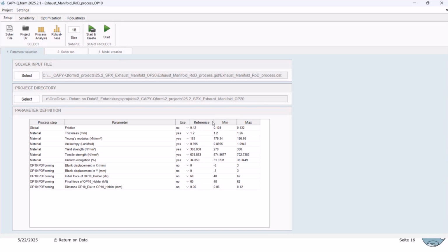so then there are two possibilities. Either you get some information from your supplier. For example, typically for tensile strength and yield strength, there is an upper and a lower limit. Or what you can also do is to say, okay, for tensile strength I take plus minus 10%, or for thickness the typical or default value is plus minus 5%. These are values to the best of our knowledge. Then you cover at least a sort of standard range around the reference value in Stampack.